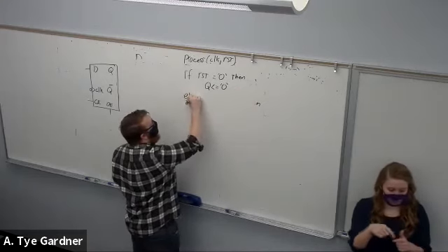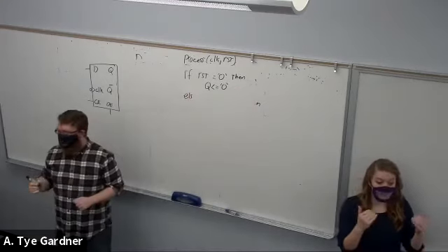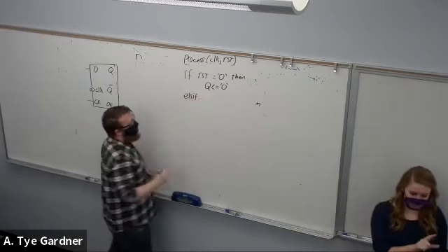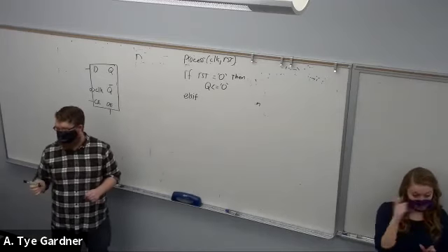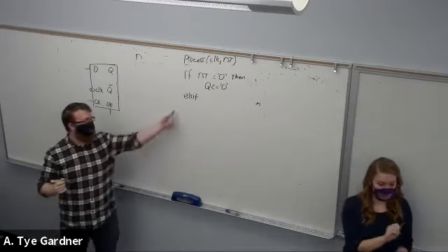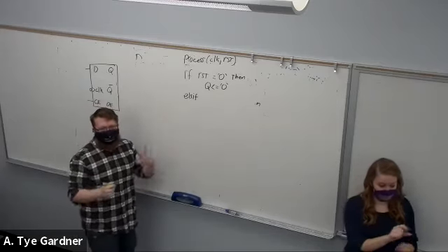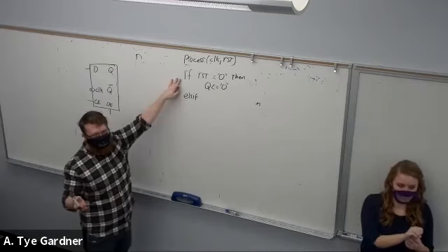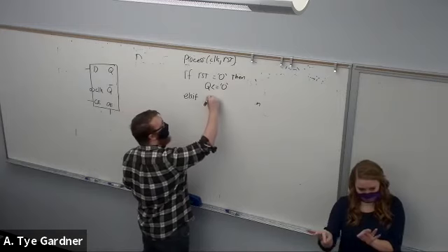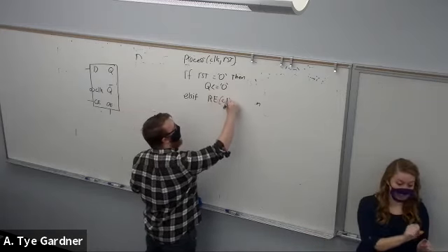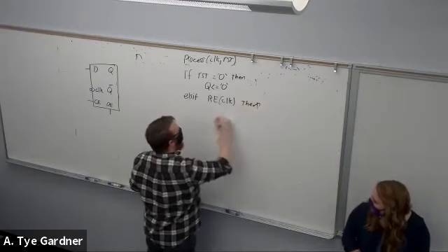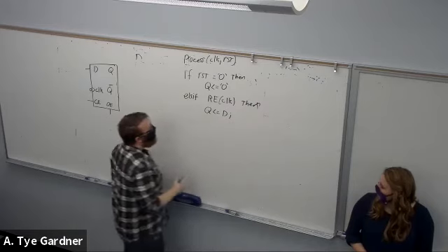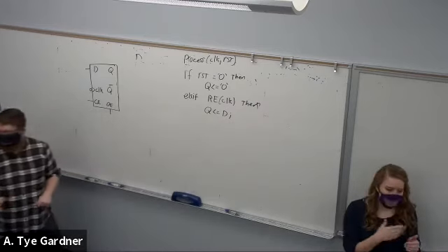Now we get to introduce the elsif statement. VHDL is kind of annoying with this because in the elsif, they get rid of the second E in else. So it's elsif. Because we don't want to say else, right? Because if you have if else, then the other one will always execute if it's not reset. Because we want an elsif rising edge of the clock, then, and then you have end if, end process, etc.